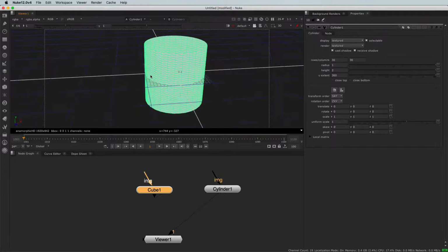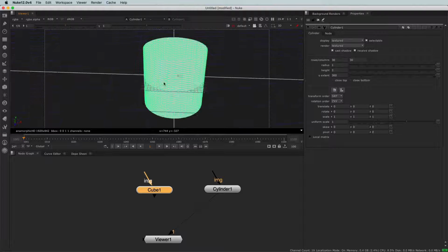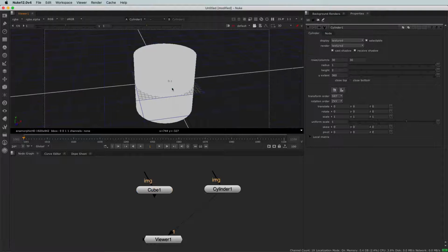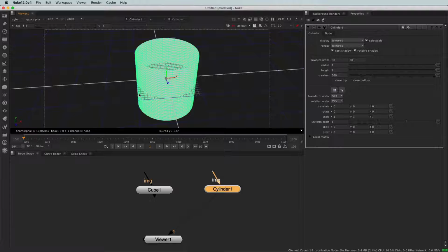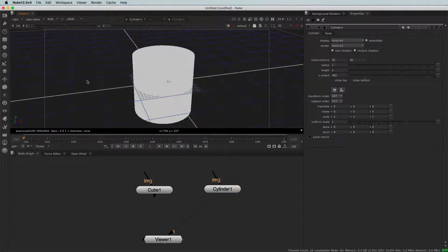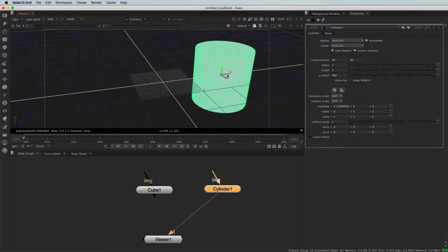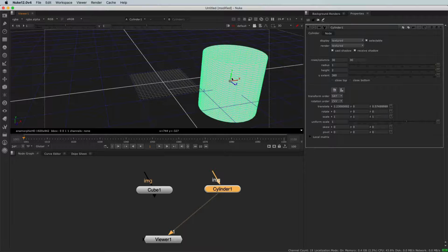All right, I know it's a bit confusing, but trust me, you'll get used to it. Now, if I want to modify a geometry, I can easily do it using that little gizmo here. So I need to select the geometry I want to modify first. Here, for example, I click anywhere, nothing is selected, even if it's displayed here and open in my properties bin. I need to click on the geometry to be able to display that little gizmo here. And I will be able, for example, to move that guy on X, on Y, and on Z.